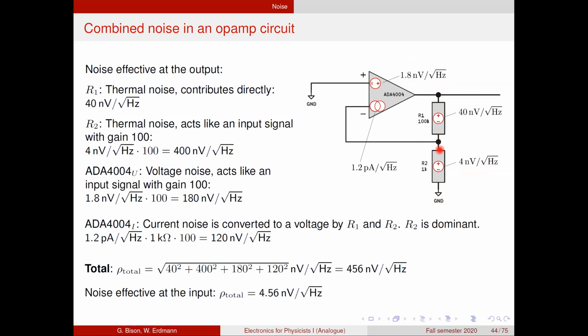If we further reduce those resistors, several things happen. The op-amp can deliver about plus minus 10 milliamps. So if we go to something smaller than a kilo ohm, then we might be limited by the current that the amplifier can produce.